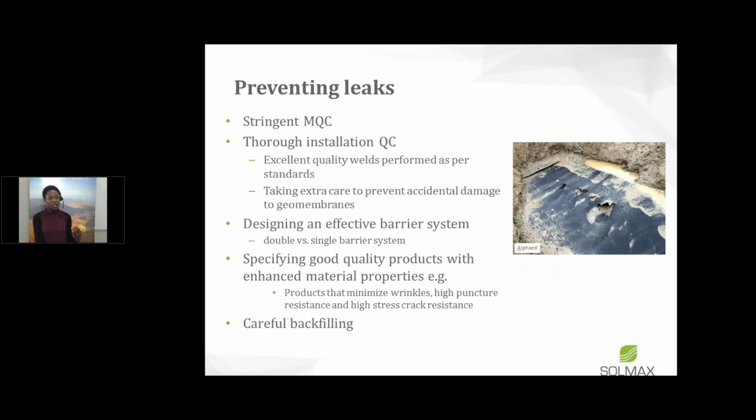And another thing is during installation, thorough quality control is required. So checking of the welds to ensure the welds have good quality, performing the welds as per standards, using the right temperature and the speed, taking extra care to prevent accidental damage to the geomembranes during installation, checking the welds for leaks, using all the methods I mentioned earlier. This can go a long way in preventing leaks.